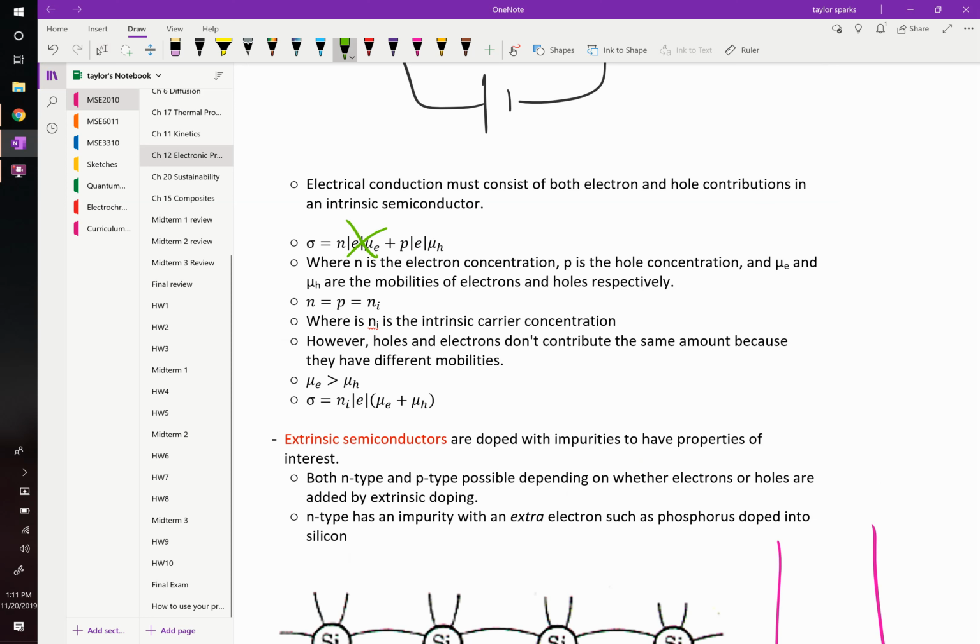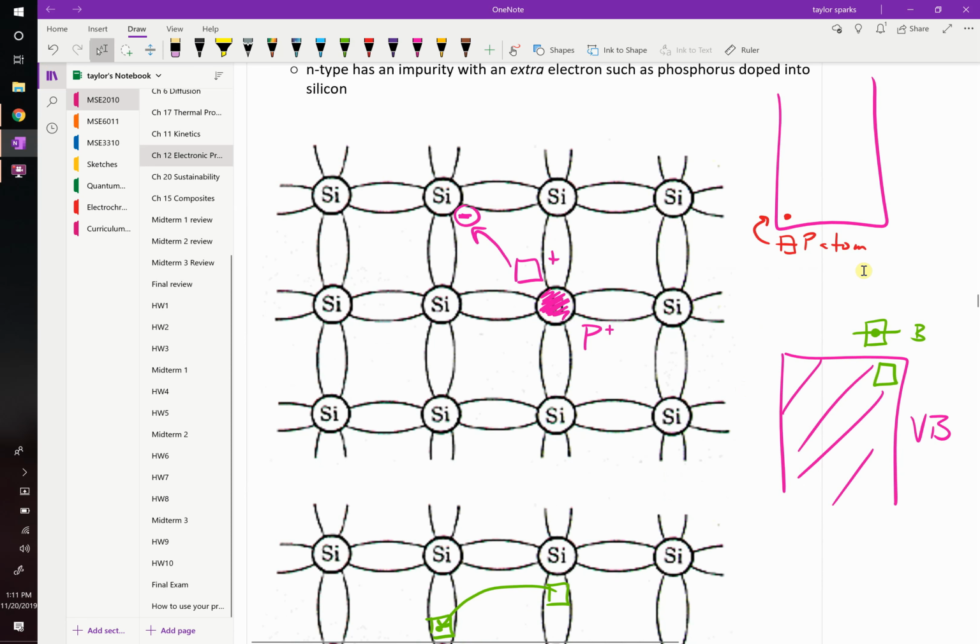So this is really important because, like the device I showed you last class, the thermoelectric device, the only reason that works is because we can make the little tiny metal legs that were standing up between the plates, those things have to be alternating n-type, p-type, n-type, p-type. It has to be holes, electrons, and I'll show you why in just a moment. Any questions on extrinsic doping? On how I got this band diagram over here?